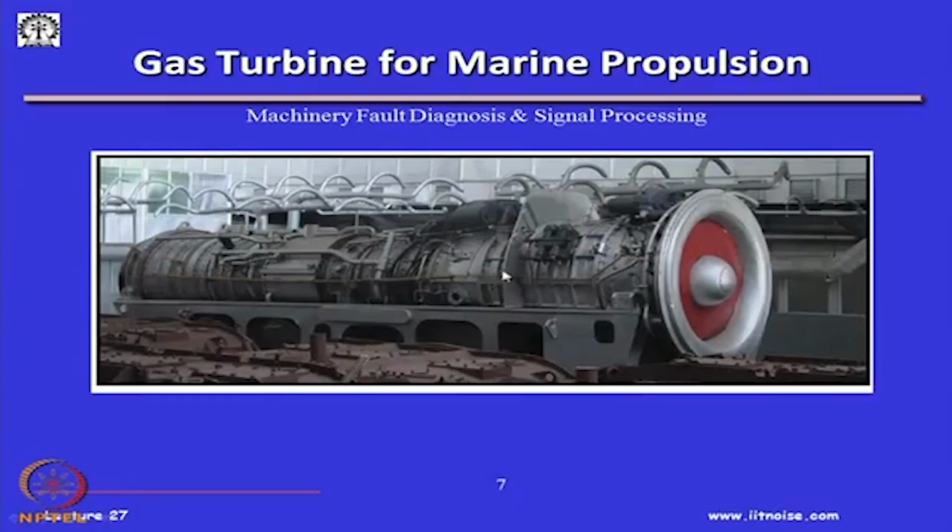Okay. So, how do you do the health monitoring of such gas turbines? The best place would be to keep vibration transducers along these rings. You will see a lot of these rings and braces, because you obviously cannot access the internals.